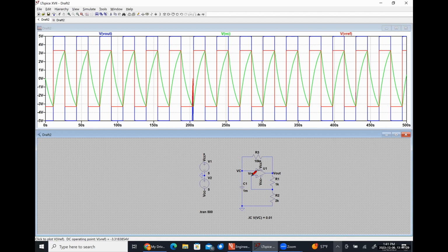If we used an NPN stage, that's just going to bring the DC level of that output even higher, so that we don't have a lot of headroom. So we'll use a PNP stage to bring the output lower, closer to the midpoint between whatever our power supply voltage is and ground down here. And then we would use an output amplifier stage that could be a push-pull amplifier.